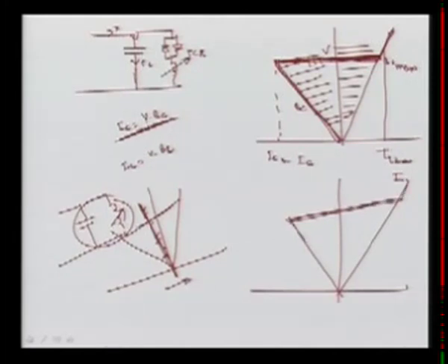So the characteristic is not 100% horizontal, we provide some slope, and this is basically called the natural regulation, and it is due to the transformer which we connect. If you remember, here it was the transformer, then we have the SVC here. So this impedance is there, so for the current which is flowing here, there will be some drop, and there will be some slope here.